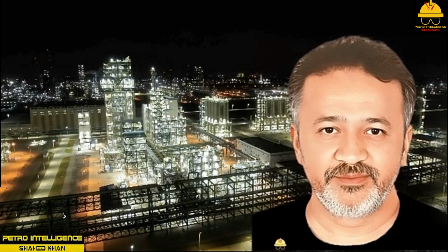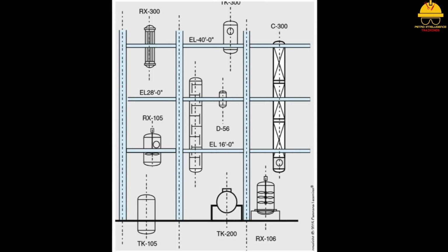Elevation drawing. Elevation drawings in this picture show the location of process equipment in relation to existing structures and ground level. In a multi-story structure, the elevation drawing provides the technician with information about equipment location. This information is important for making rounds, checking equipment, developing checklists, catching samples, and performing startups and shutdowns.